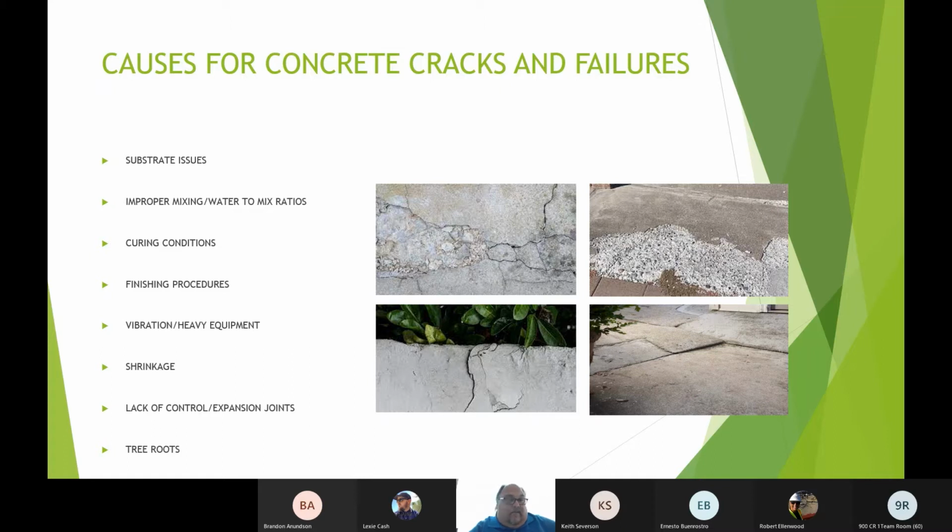A lot of the issues can start with the bad substrate. Bad substrate issues include improper design of the substrate, no proper drainage, lack of rebar, lack of reinforcing wire, dobies, insufficient soil and rock compaction. And it's really important to address the site and the condition of the soil and the substrate underneath what's going to be on that concrete pad. You want that concrete pad to have a nice, even, stable, secure location to sit on.